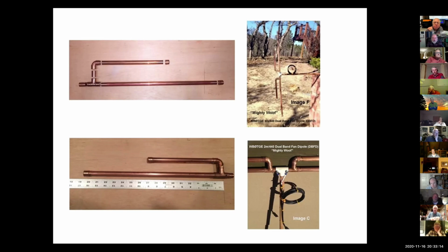Afterwards, when you take the torch away and the solder away, you can take a damp cloth and wipe around that joint and make it a nice clean joint. Soldering is just a skill you can learn in about 3 minutes, just playing around. It's not a very hard thing to do.